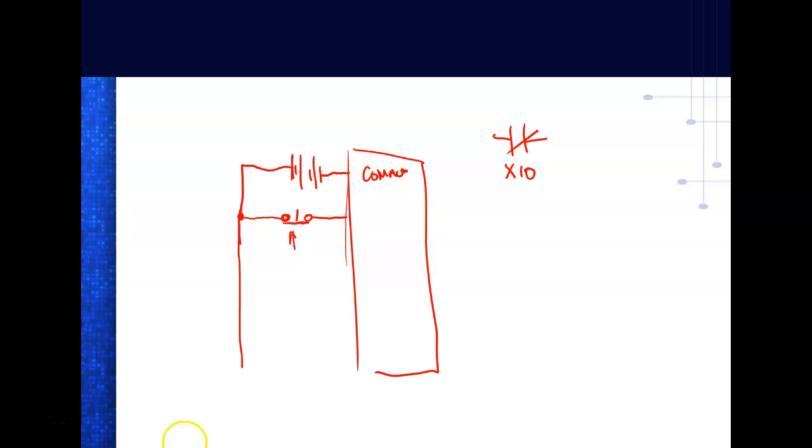What I should use here is one of these. This is examine if closed. We want it to be true because it's a normally closed push button. We want it to be true, right? You understand that? So this is the one we would use in our program. If he's using a normally closed push button and he's using this instruction right here, then that will start off false. When I'm dealing with contacts that are not from an input, then normally closed, normally open is perfect. But when I'm dealing with actual true inputs, then this is going to cause a problem.